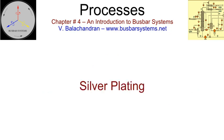Silver plating. Silver is an excellent conductor of electricity and therefore provides the least contact resistance. For the bolted joints, a thickness of 10 microns is adequate. Silver plating is expensive. The requirement of the thickness of silver plating of contact surfaces of switchgear is higher as it has to cater to impact, abrasion, and arcing.